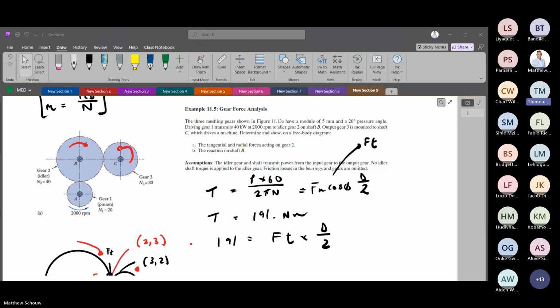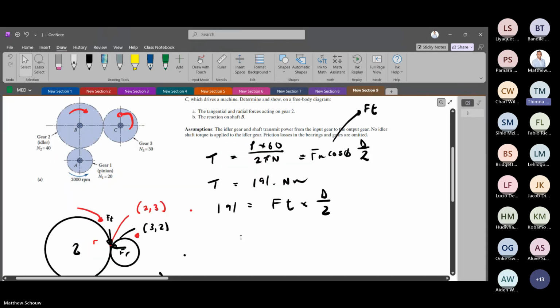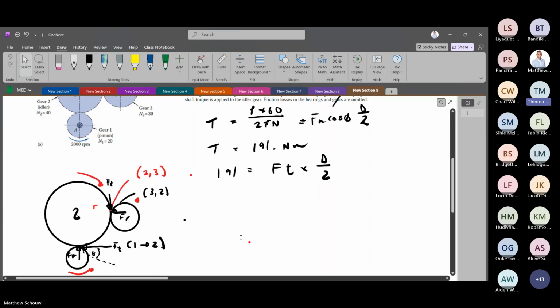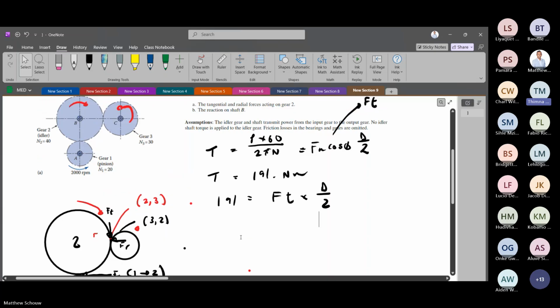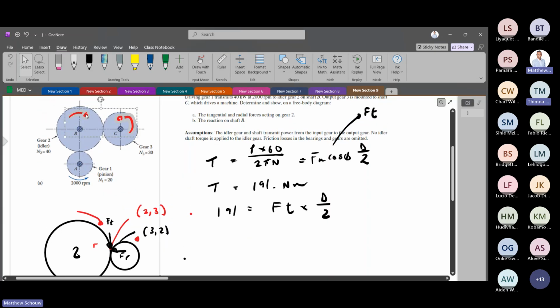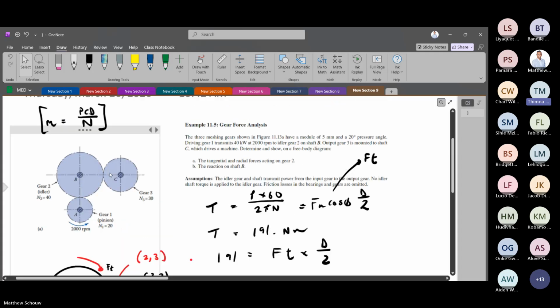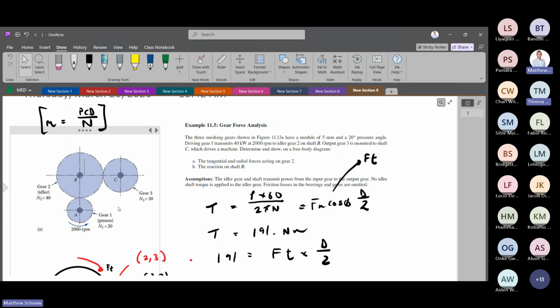For the direction of gears, I think there's a method or a golden rule we can use to note that direction. For example, if the number of gears is odd, then the first gear's direction will be opposite to the last gear's direction. That's correct. But if the number of gears is even, then the last gear and the first one will be in the same direction. That's correct.